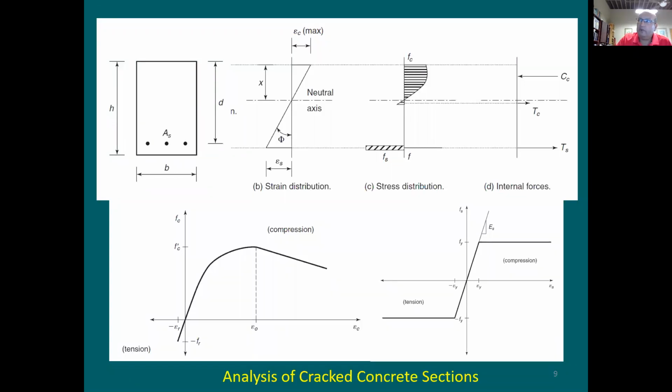Now you start to apply more loads, the beam is gonna crack and the crack is gonna start here from the bottom. So what happened to the total depth? It's gonna get reduced. Why reduced? It doesn't mean that H is gonna become smaller, it's not gonna become 20 inches. But what I'm saying is, because the bottom is gonna be cracking, the effective depth is gonna drop down. Instead of 24, it's gonna be, let's say, 20 inches. So the bottom few inches from here is gonna be cracked. So the effective section of the beam is gonna be right here on the top.